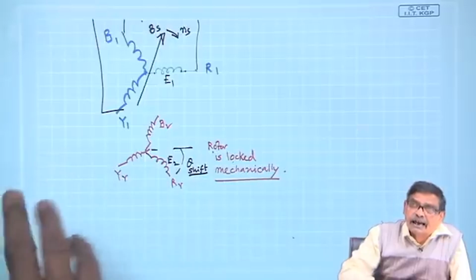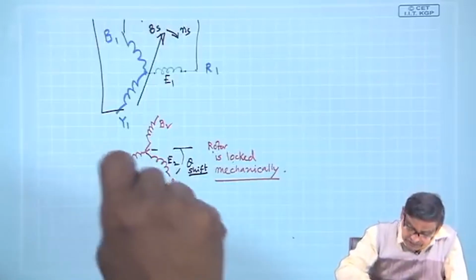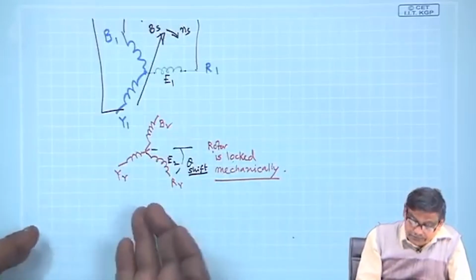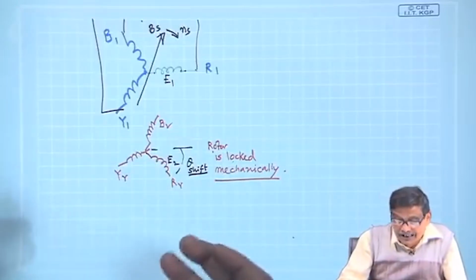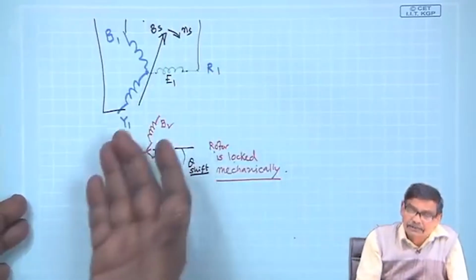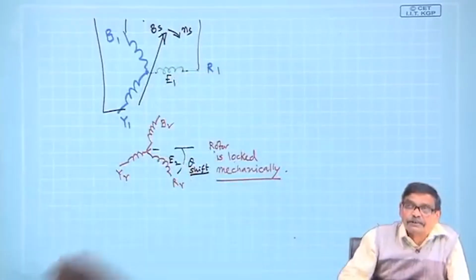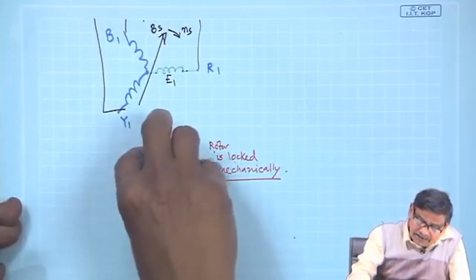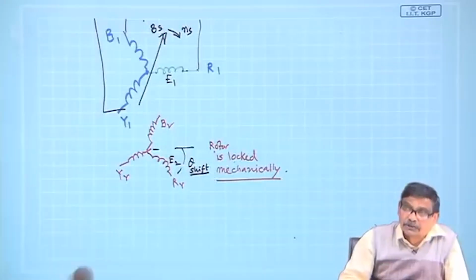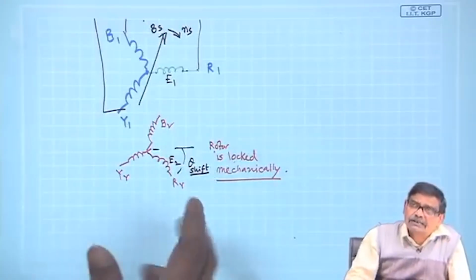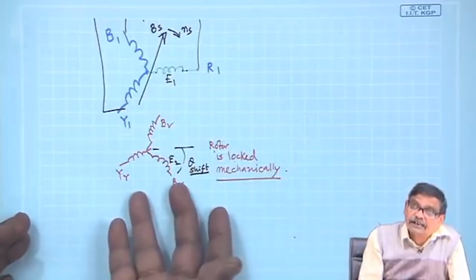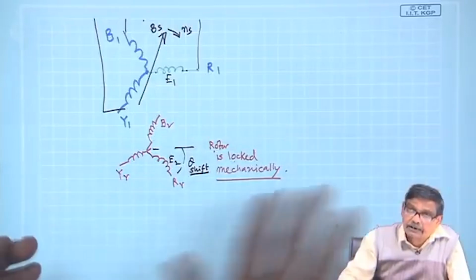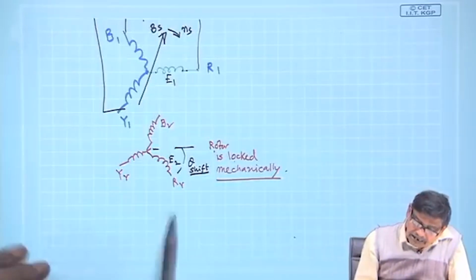There is a calibrated dial, you shift it, physically rotating it. Initially the manufacturer will calibrate it, because from outside I can see neither the R phase of the stator nor the R phase of the rotor. It can be done easily even if it is not marked: I see where these two voltages are in phase, then I say the R phases are coinciding. That way you calibrate.